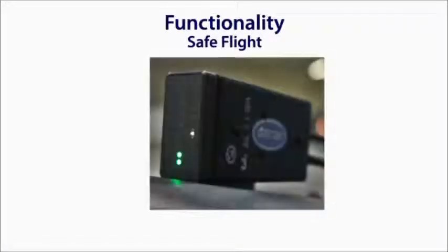The Safe Flight device features an on-speed indicator and a series of multicolored dots that indicate whether the aircraft is over or under speed. Additionally, the device has settable bugs to be used for various different maneuvers. The device gives a Geiger counter warning when the aircraft is approaching stall. This warning is usually in advance of the installed stall system, which gives the pilot advanced warning for stall avoidance.